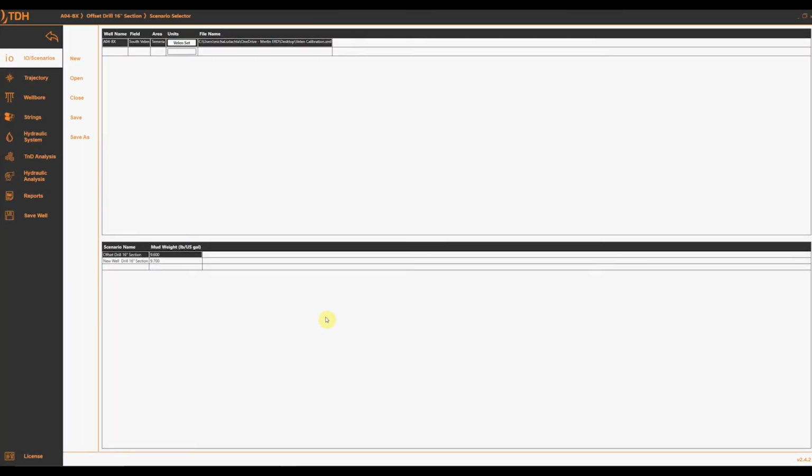Okay, so today I want to show you how to properly hindcast an offset well friction factor, and how to use it when planning a new well. I have two scenarios in here. The first one is the offset well that was drilled sometime in the past in the field, and I'm interested in what kind of friction factor to expect when drilling in this field, and that means also what kind of loads to expect when drilling a new well with the same friction factors.